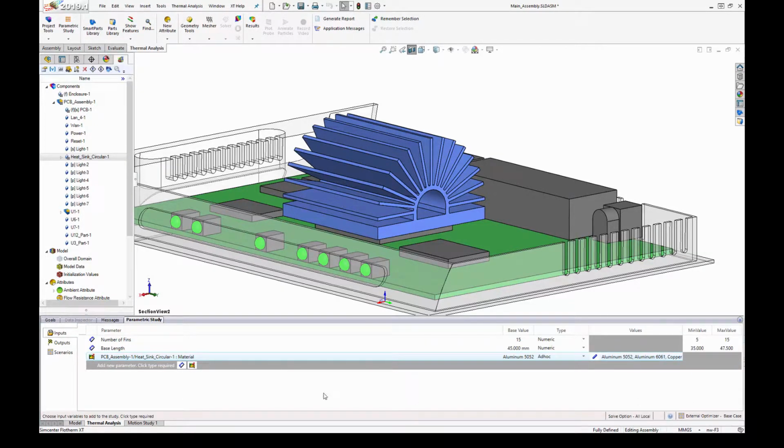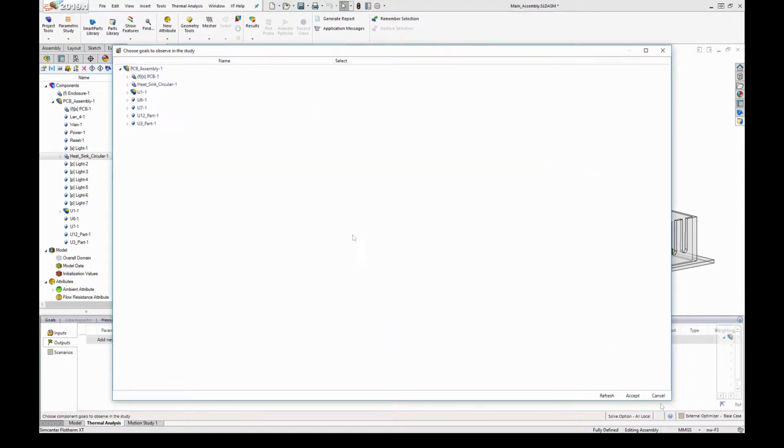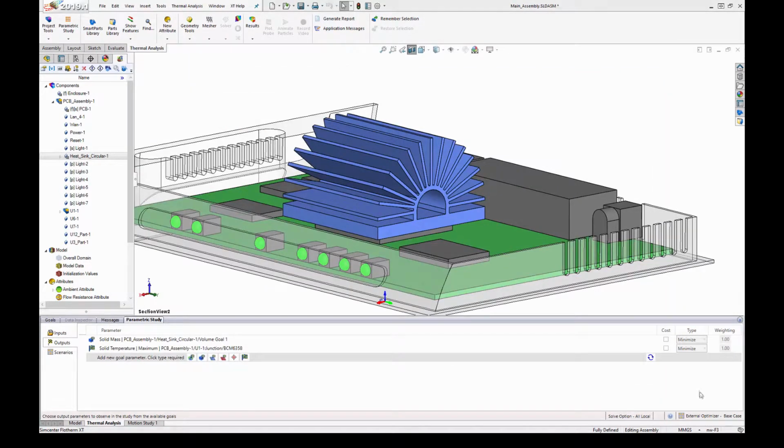Cost functions for the optimization process are usually set in the external tool. It is also often possible to define constraints on the input or to define a study to say minimize my heatsink weight but ensure that the junction temperature does not rise above 90 degrees C.